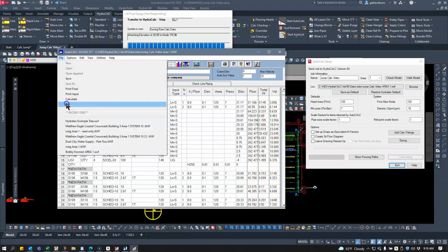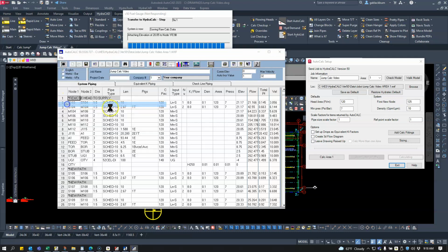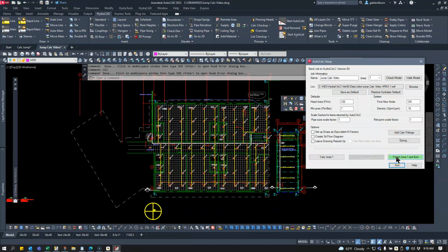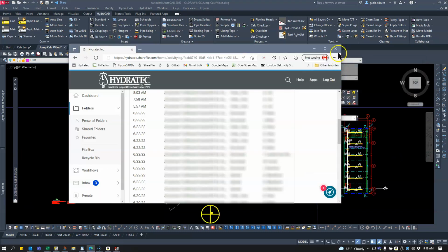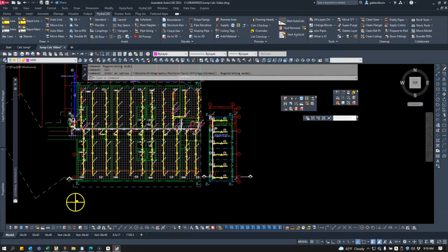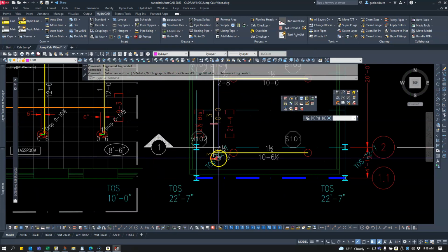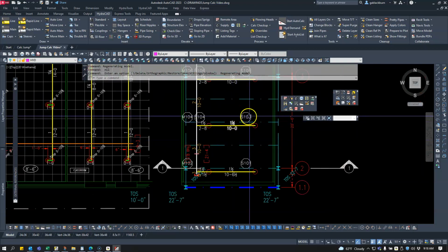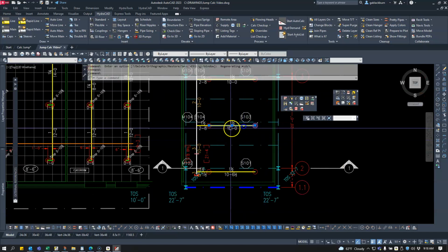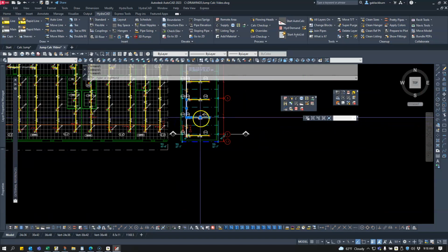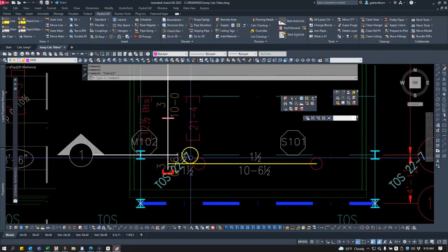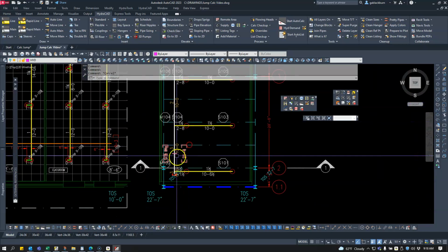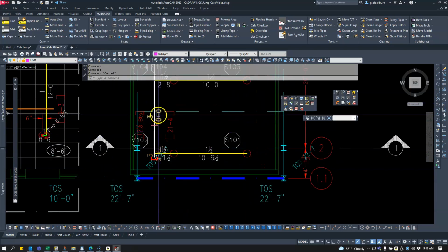I will file. I'll click save, file, exit. It's going to return back across. Go here. I'll finish area 1, and let's minimize that. And there we go. And we can verify here that was supposed to be 2-inch. Oh, because this was my remote head, I only changed these diameters all the way back. I did not tell it to look for this diameter. So this did not get part of that calculation. That's the reason why this is still 3-inch.